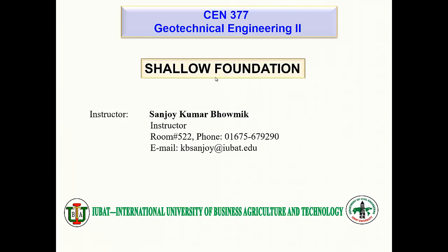Additionally, we also studied how we can extract the soil parameters from the N value of the SPT test, and how we adjust the N value to N60, N60 to N1,60, and we developed some correlations with the soil properties. Once we know the soil properties, our next step is to know about the foundations. In this chapter especially, we'll be discussing the shallow foundation.